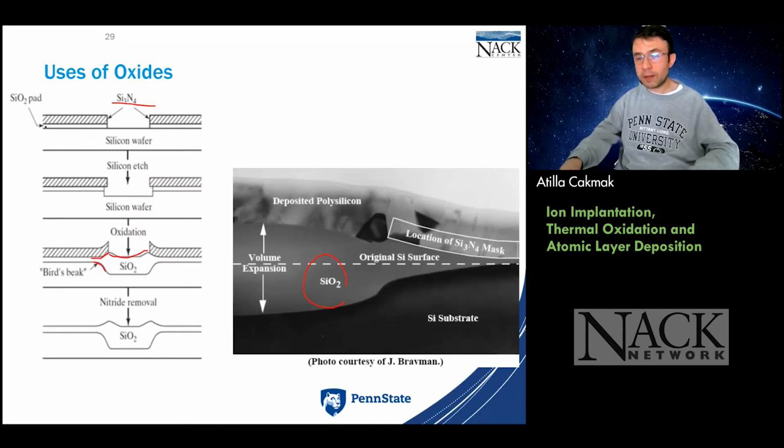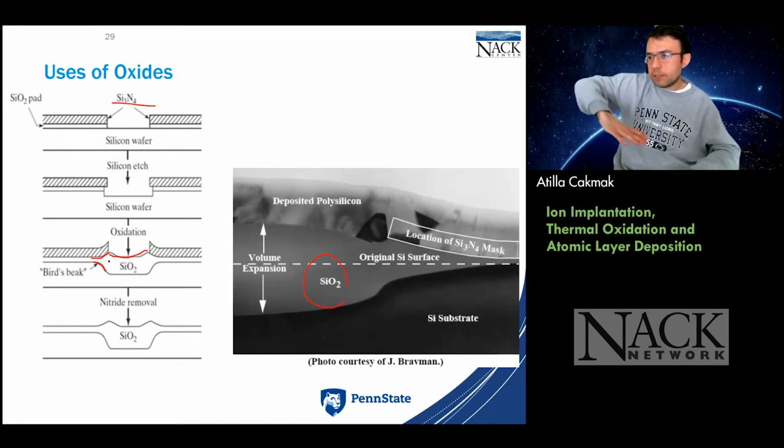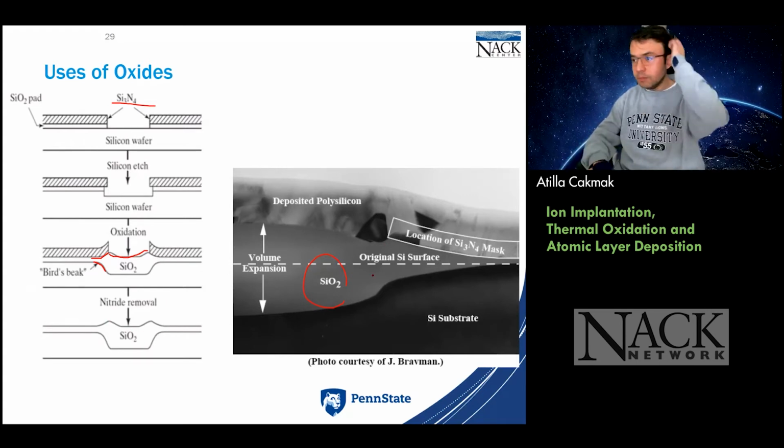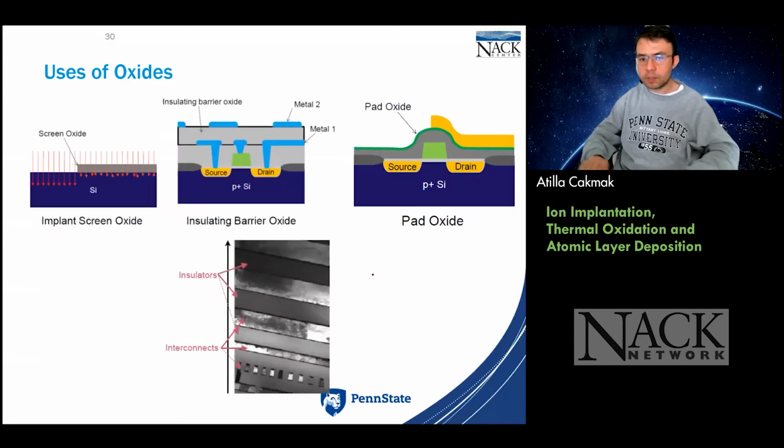Look, underneath the silicon nitride, there is a little bit of a connection coming from what we call pad oxides. That's another form of oxide just underneath the silicon nitride. They connect, and because of this growing layer, it puts a stress on the silicon nitride that it can withstand. And then once we remove the silicon nitride, we have found our LOCOS layer. That's how it's made, from the volume expansion.